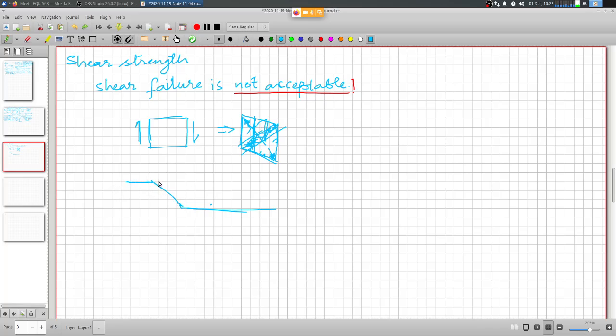and then take it to the compression zone. So you would have different levels of reinforcement being bent up at different levels, right? And if you look at it, these diagonal bent up bars are actually aligned with the diagonal tension that is required to withstand the shear.